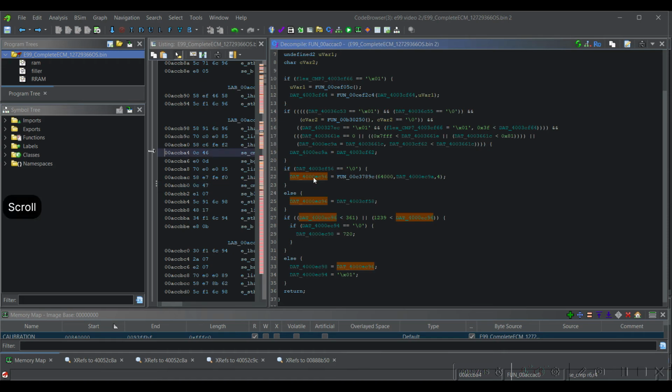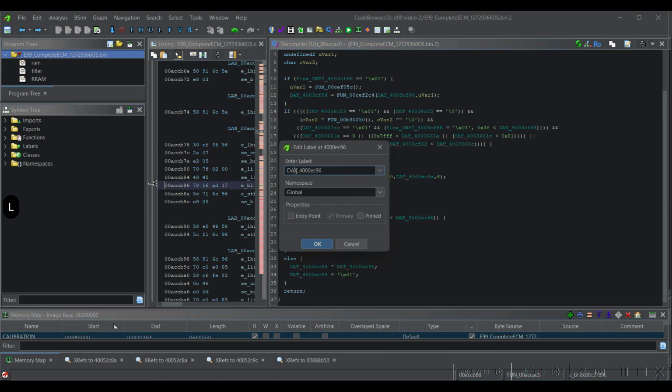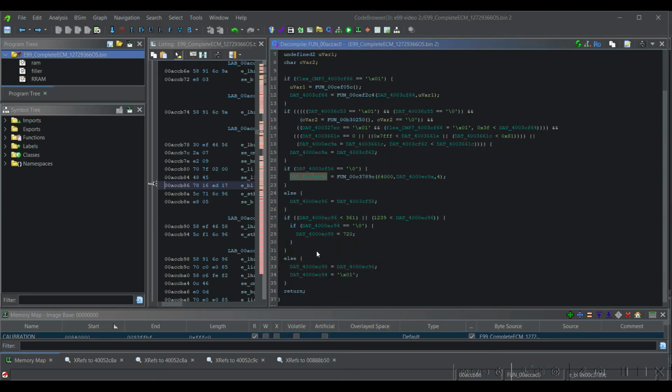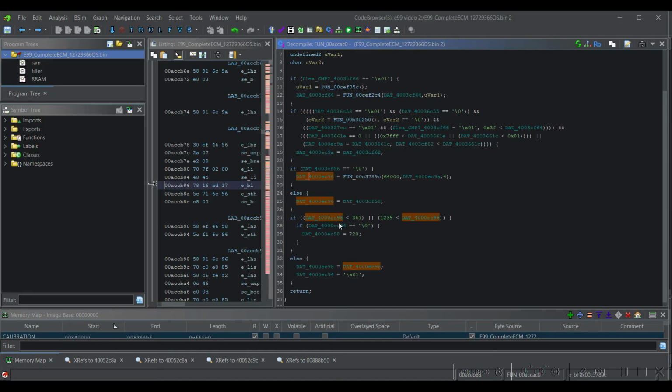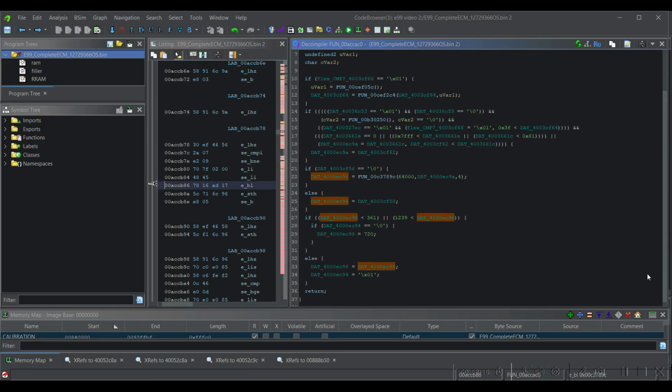I would label all of these, you know, flex look at me or look at me, and I would dedicate some time. If you want to understand reverse engineering this flex fuel system, you need to end up tracking this variable to SAE PIDs, to SAE DTCs, or to an axis of a map that then you can infer what this is. You know, maybe it's lambda, maybe it's ethanol content, maybe it has an effect on your spark tables, right?